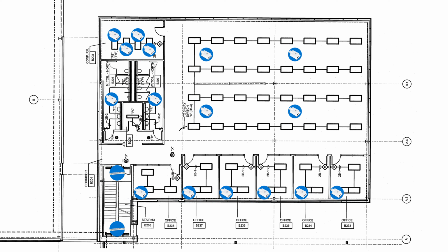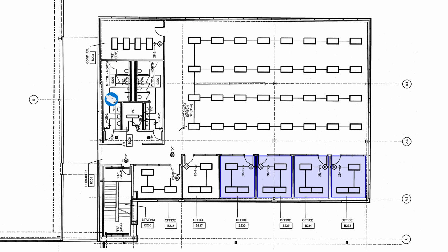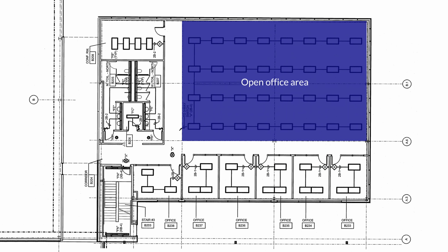With each smart driver and advanced load controller, we include a shaded blue region which defines the fixture or fixtures controlled by that device. In some cases, the pre-existing circuitry will need to be modified to accommodate the newly proposed lighting zones. Let's talk about how that would be done in the open office space of this example.